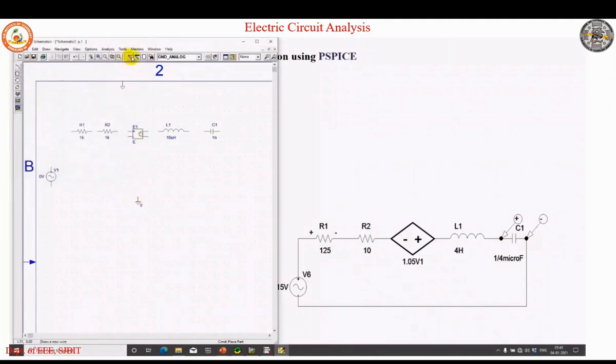Okay, now we have got all the parts. Let us connect them. The keyboard shortcut is Ctrl W. The one which is encircled is a dependent element, and the one which is not encircled is your independent element. So this is the dependent element, which is encircled. In a rhombus here we have plus and minus. Similarly, over there in PSpice, in the circle we have plus and minus.